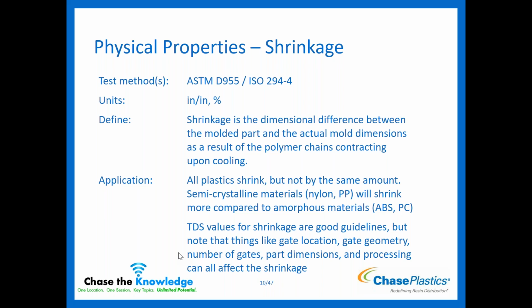So just note that all plastics are going to shrink. It's what they do, but not always by the same amount. Your semi-crystalline materials that are more crystalline, they have to expand more to be molded. They're going to shrink more compared to your more amorphous materials, your ABSs, your PCs.